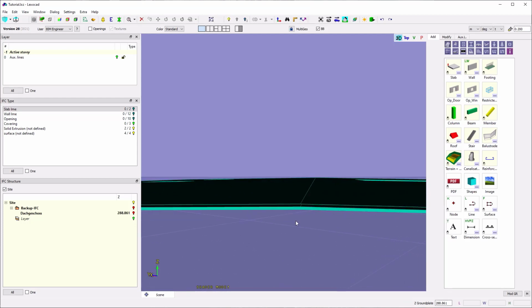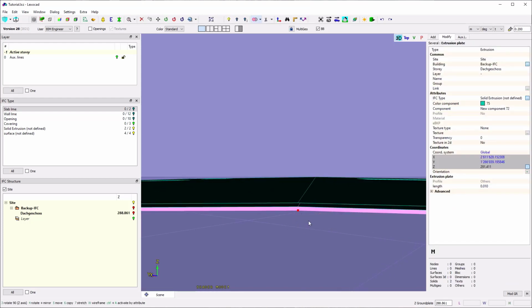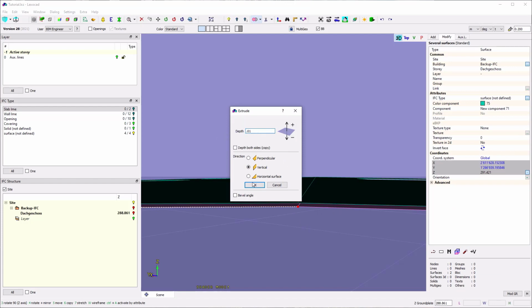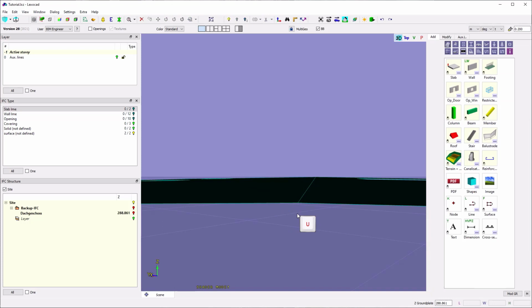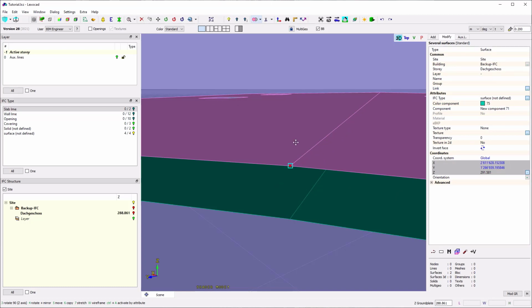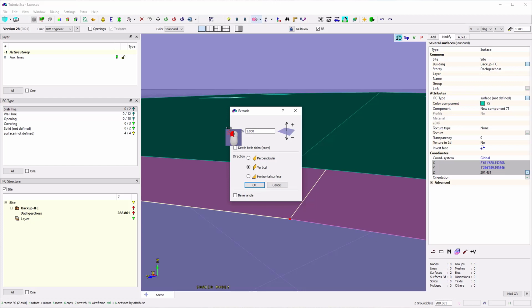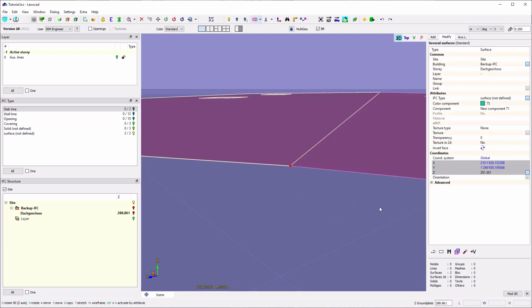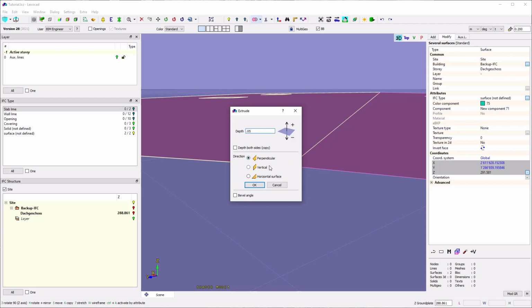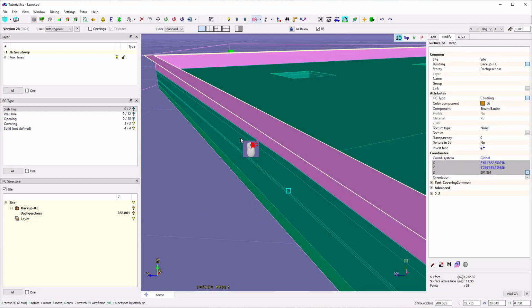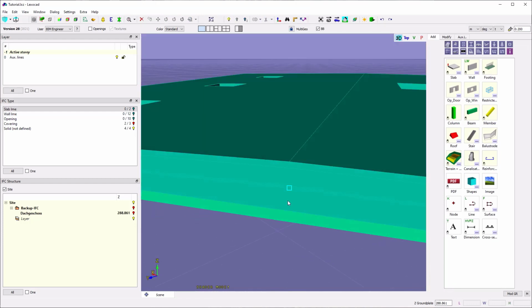So we can hide this element or take them both with the D button. We got one element. Here we do the same, vertical 1 centimeter. Take them with D and hide it with U. Now we have here the plant substrate that is 10 or 15 centimeters for our example. So we take them, make here the 15 and take them with D and hide it with U, and here our last element, that's a greening with 5 centimeters for example. So vertical, perfect. Now with J we got all our elements, hide the steam barrier, so we have now our layers.